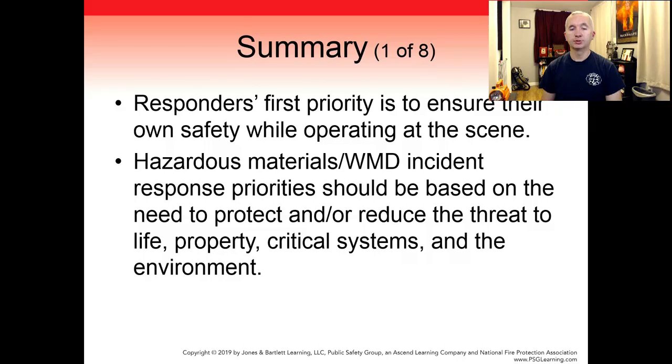Tactical control objectives should include preventing further injury and controlling or containing the spread of the hazardous material. Response objectives should be measurable, flexible, and time-sensitive. They should also be based on the chosen strategy. Defensive actions include diking and damming, absorbing and adsorbing the hazardous material, stopping the flow remotely from a valve or shutoff, diluting or diverting the material, and suppressing or dispersing the vapors. The decision to act at a hazardous materials incident should be based on the concept of risk versus benefit.